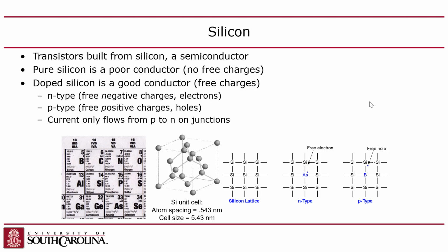So that's a diode. Now, the thing that's a little weird about this is the next step you have to take to understand it. The majority carriers in P are holes, as I mentioned, and the majority carriers in N are electrons. But there are also minority carriers. So even though P has all these holes in it, you also have some electrons in there as well, but not many. And you've got some holes in the N-type silicon too. Those are called the minority carriers, right?